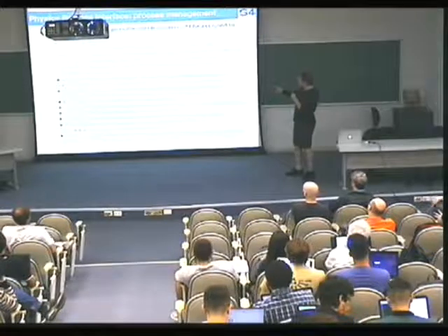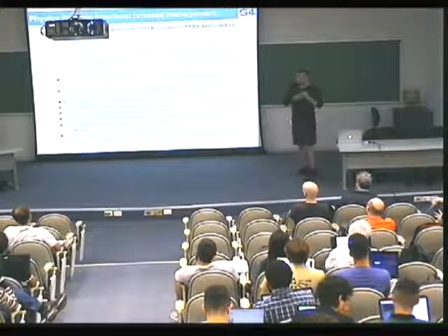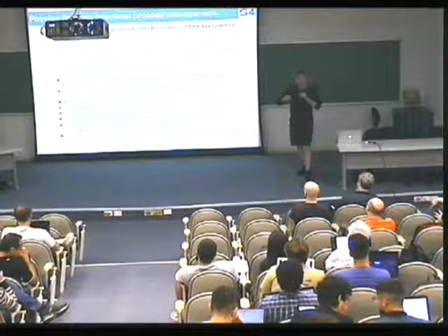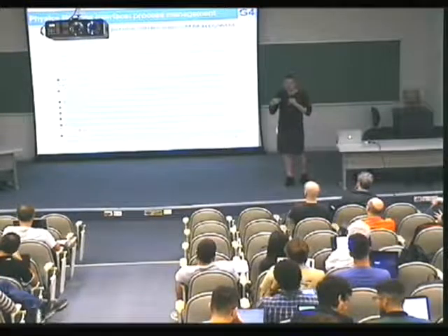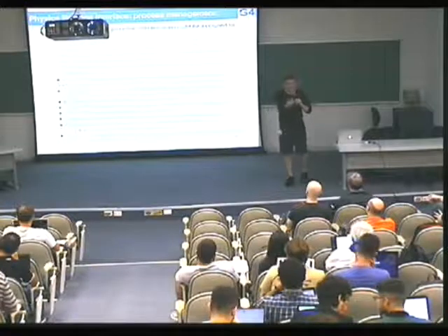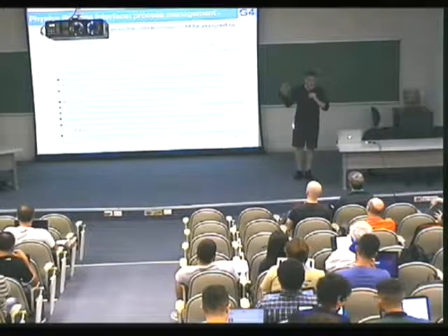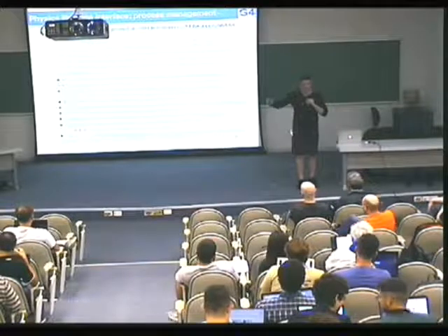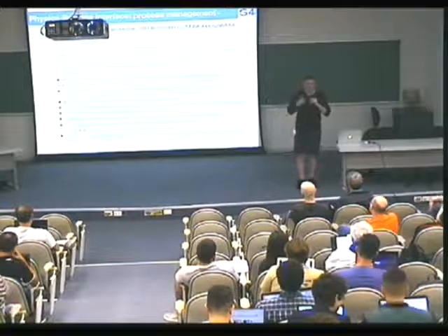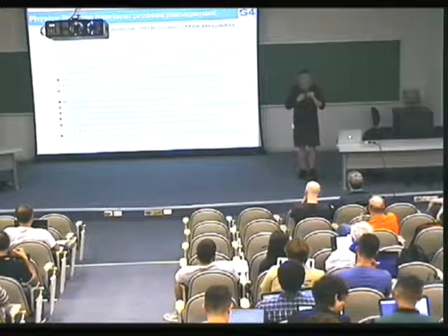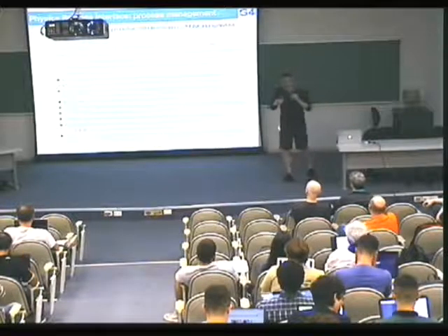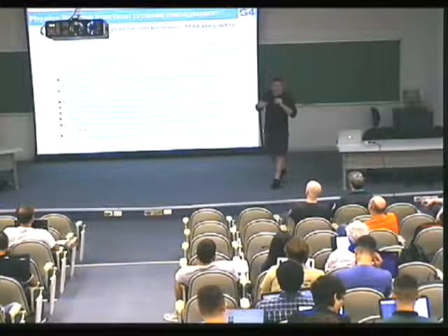And as we saw, this G4 process manager is storing this list of processes. During the tracking, we can always have access to this list, as the process manager can give us the list of the assigned discrete processes. If we have a particle like a gamma particle, we can always ask for the list of the discrete processes, the list of the continuous processes, the list of the at-rest processes.